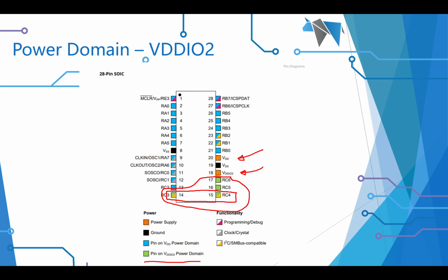as my I2C circuit. And why is that? Because it says down here, look, that they are compatible. So that relates to that, and this relates to this. So you've got a bit of a, not a Venn diagram, but it could have been. So you need volts up here, volts here, and for those that remember, I've still got coming out of RC6, the TX, the transmit to my serial, and that's what we're going to look at. So your connectivity is critical. You must put the VDDIO2 circuitry up.